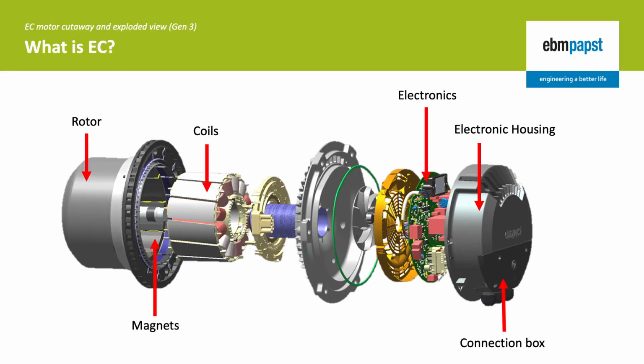EC stands for electronically commutated, which basically means that the fan uses an electronic controller to operate the motor windings instead of switching voltage of the AC mains, or in the case of DC motors, using physical metal brushes.